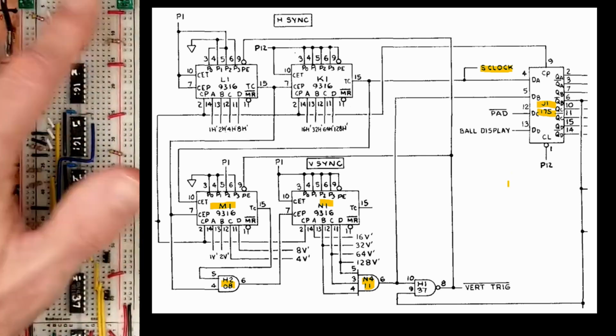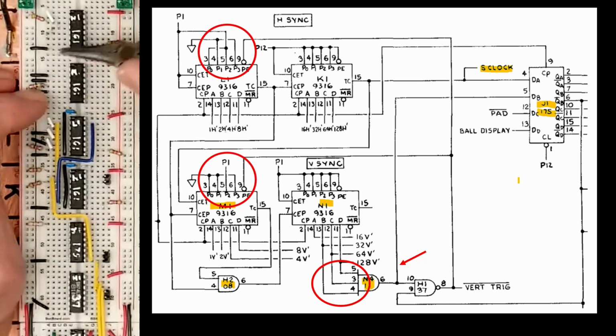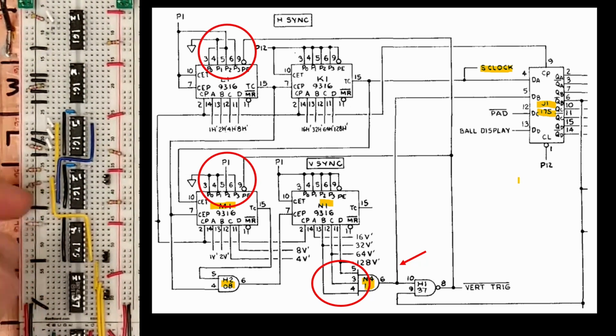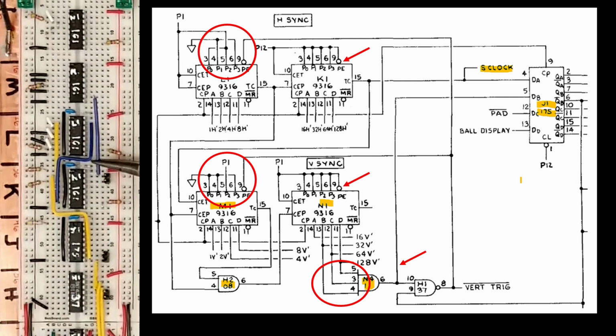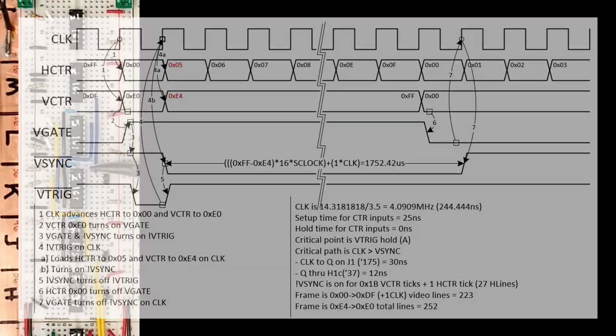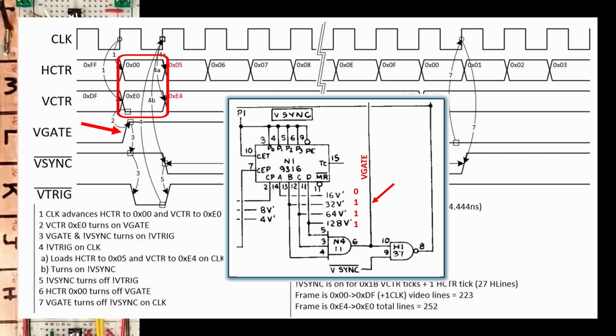When a high order vertical counter reaches 1110, it raises this line, causing the loading of new values into the low order counters of both chains. You'll notice that the high order counters are never loaded and maintain their state. If we diagram this out, when the counters roll to E000, this line goes high. Well, we'll call it V-gate because it generates V-sync.